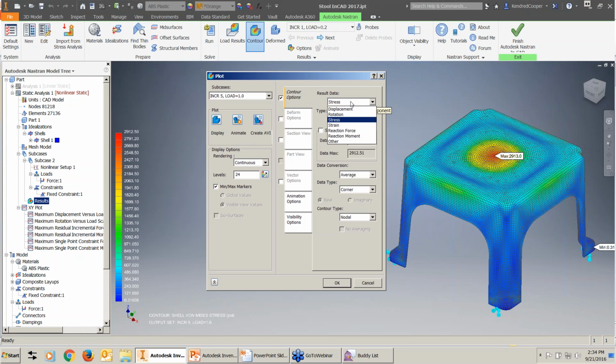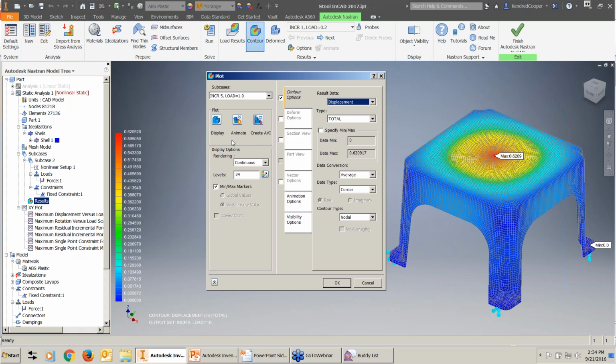Let's look at the amount of deformation. When I switched to deformation, we were displacing over an inch, averaging 1.25 inches. We're now displacing right at 5/8 of an inch. So we've cut it in half. That seems a lot more expected. 5/8 of an inch, yeah, that's still a good bit of movement, but nowhere near like over an inch. That's what I would expect to see happen when somebody stands on it or when a child sits on it.